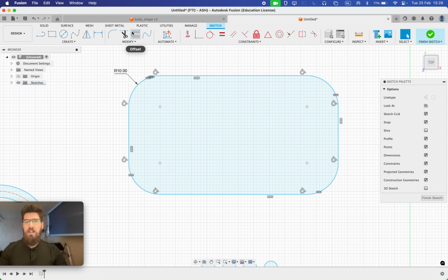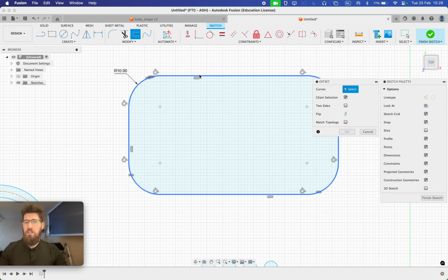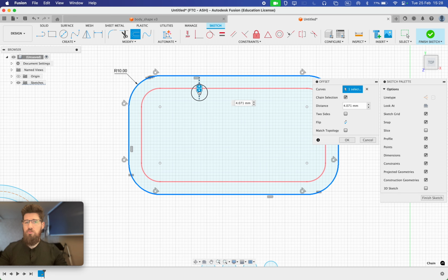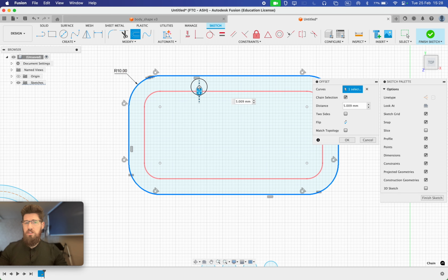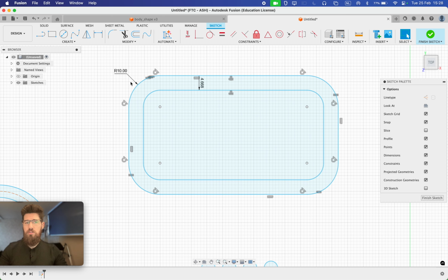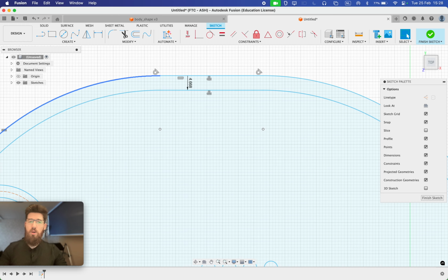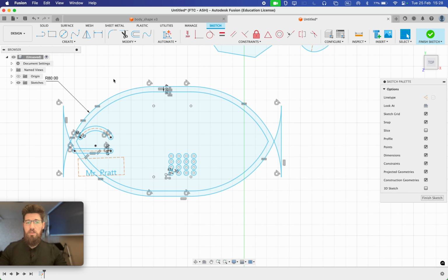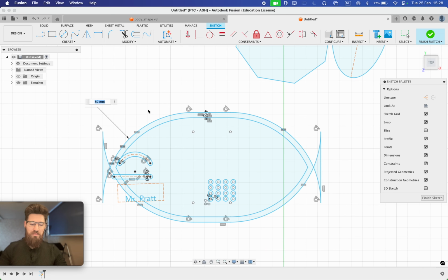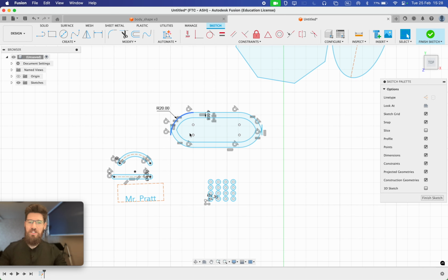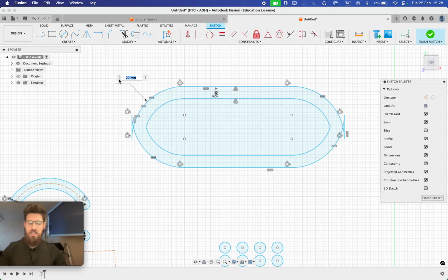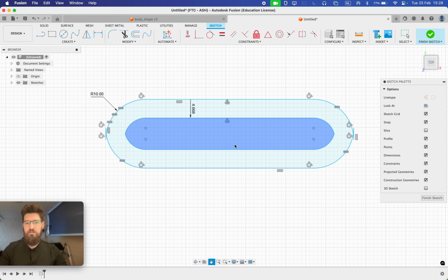You can also add in an offset. So if I were to click on my outside line, I can go ahead and drag in my offset tool. The nice thing about offset is that it's going to match whatever changes I make. So the offset automatically propagates over on what it is that I'm choosing. Oh, that's a really funky shape, making that a radius of 80. Let's make it back to 20. Oh, that's still a little funky. Let's make it 10. All right.